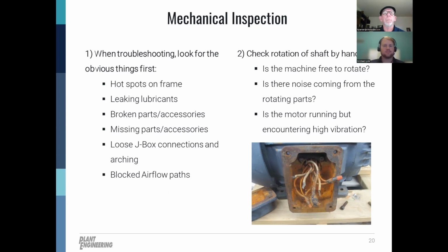through your fan. And then some of these things aren't very complicated. You've got somebody who's doing work around the motor, and then they leave a cardboard box or papers out on the job site or out in the plant, and then the motor starts running. It may suck those papers up on the fan shroud, and then now you've got your fan blocked, or a box that's sitting too close to the motor and it's limiting the airflow coming into the motor. So definitely pay attention to that. Keep the areas around your components clean.